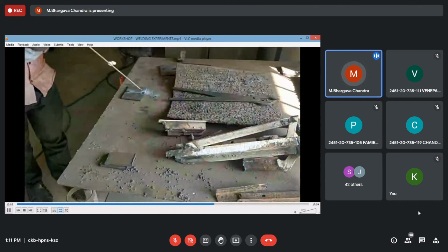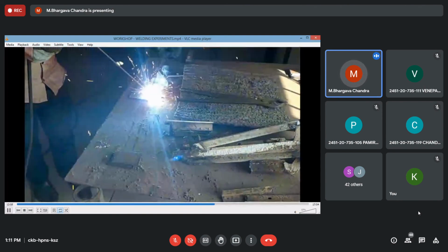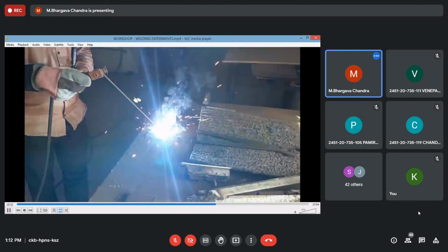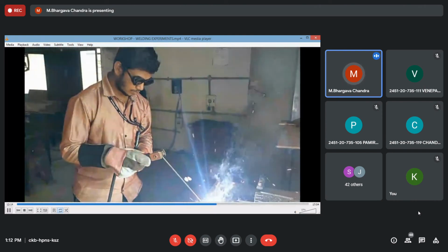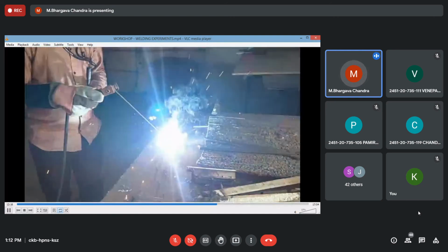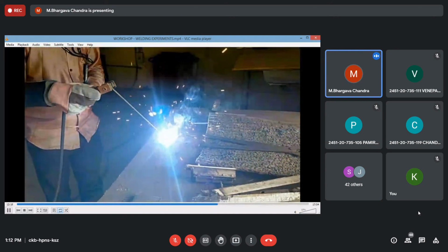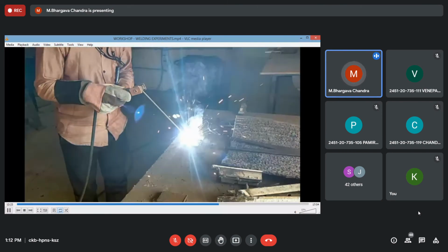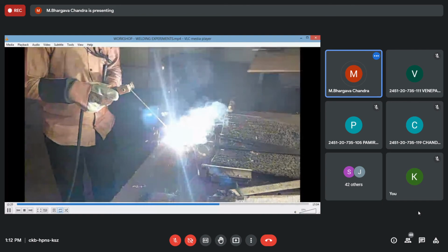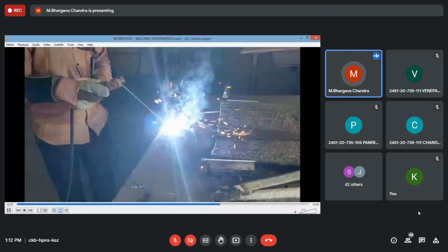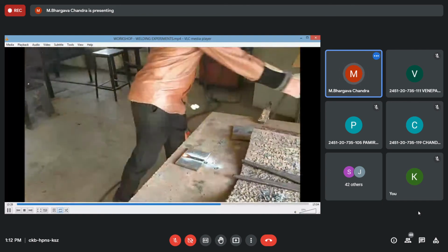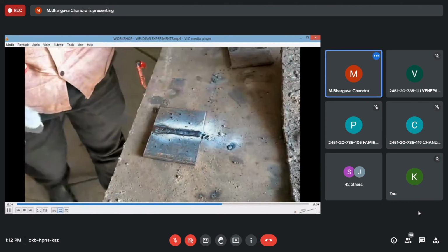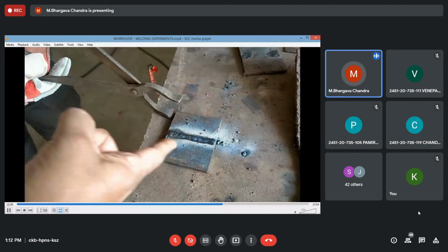So, you have to do the beveling operation and allow the extra space which can hold the welding material. Additional welding metal can be held in this V notch. It should create a strong joint here. The welding rod gets consumed here, becomes molten and gets deposited into the workpieces. So the total V notch is filled by the welding material.